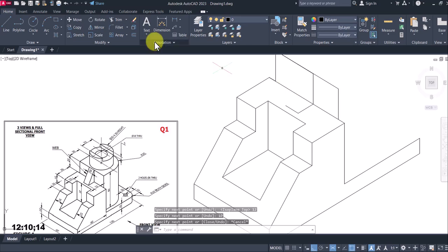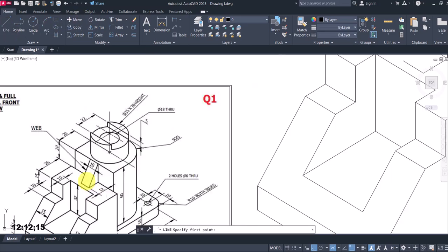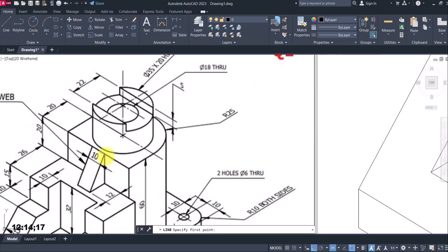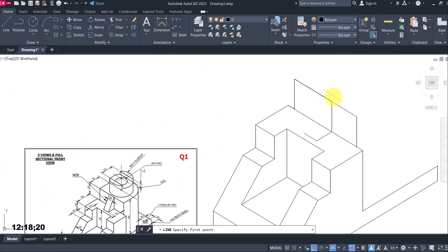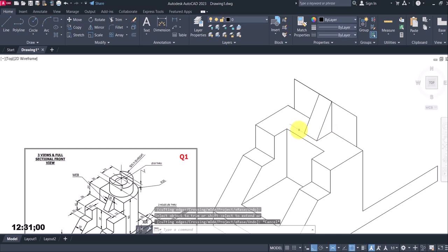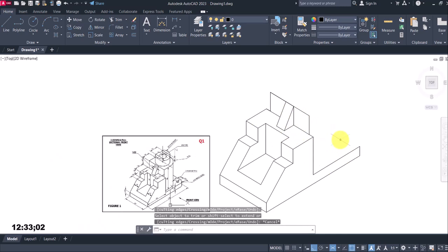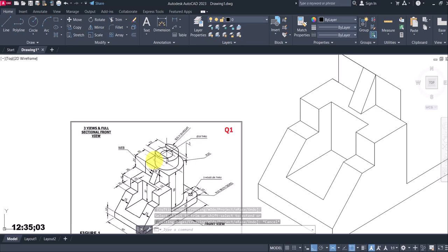Okay. All right. So now at this point, this line here is not an isometric line, but I'm able to get to the two endpoints of the line. So I can just connect this and this. Connect, then I can make a copy of it to get this. Then I'll trim off the necessary intersection lines. So I'm able to draw this wedge. So I'm getting to the end of this drawing.